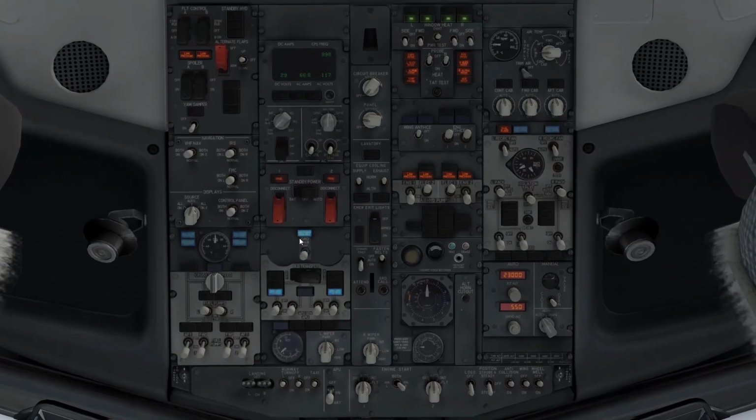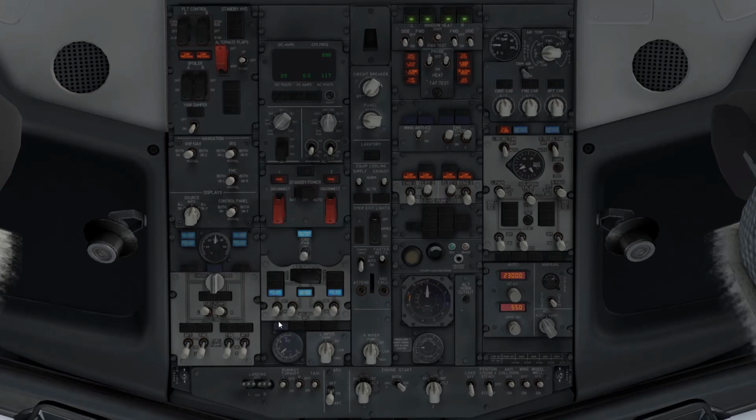We have ground power connected. Once we have ground power connected, this light illuminates, so we can go on the ground power. And we can turn the APU bleed off. Turn the packs off as well. Sorry, I should have earlier put that isolation valve to the open position, but the ground crew would be hooking up conditioned air probably around now. We can turn off the APU. Fuel pumps can all come off as well, and we can do the parking checklist.